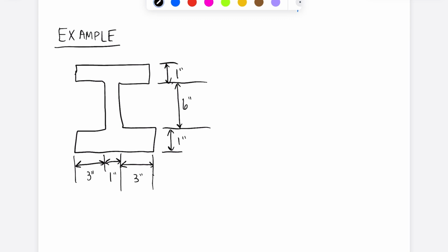Okay, so I want to know the center, the centroid of this body, and we'll talk about a different method for doing this in the next video, but one important shortcut that you can take is, take a look, is your body symmetric? Well, looking at this one, I'd say it is. It's symmetric about this center, right? It has 3.5 inches on the left side, 3.5 inches on the right side. So this body can be mirrored across the red dotted line that I've drawn here.